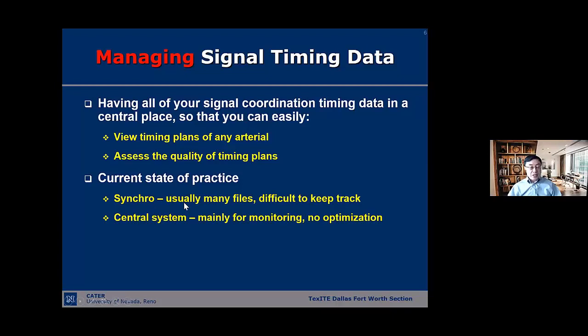But in most cases, they have Synchro files, but usually many files. They created many files, and they don't even know whether the timing in those Synchro files really matches what's in the field, right? That's what I'm talking about. So very few agencies actually have a place where they store all their signal timing data. So somebody may say, yeah, we have the central system.